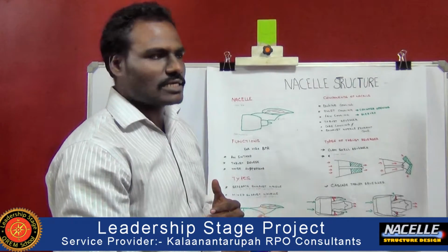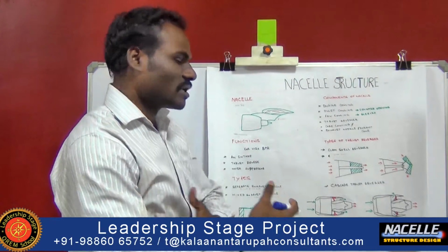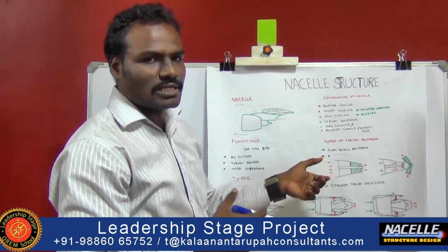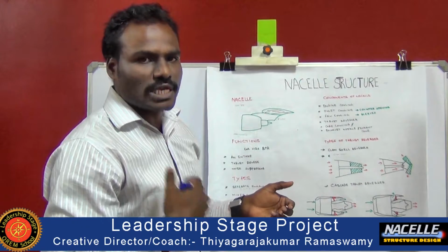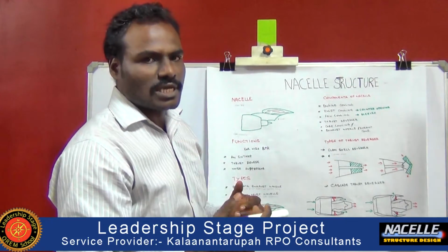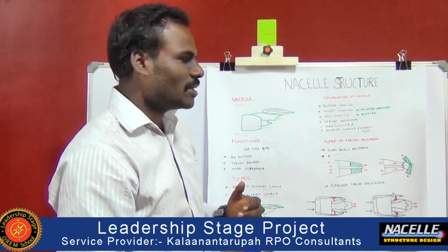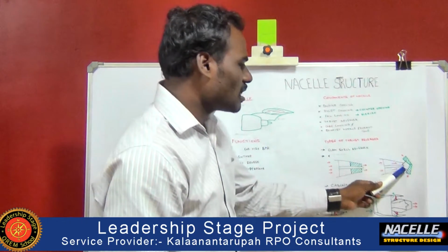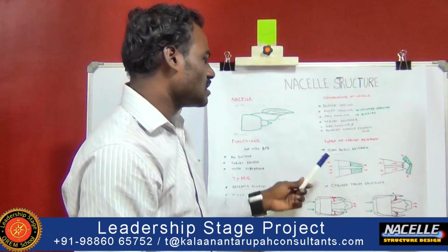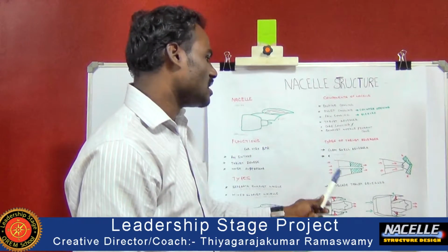the inlet gas, that is the gas which enters the throat, as well as the gas which passes through the engine where the combustion process takes place, and the thrust which is ejected from the nozzle is also controlled and subjected to a backward pressure, so that it helps us in the thrust reverse process in the clamshell reverser.